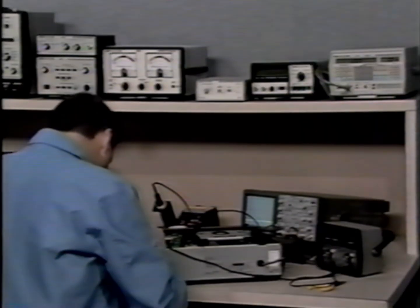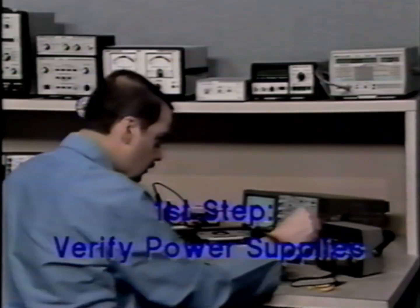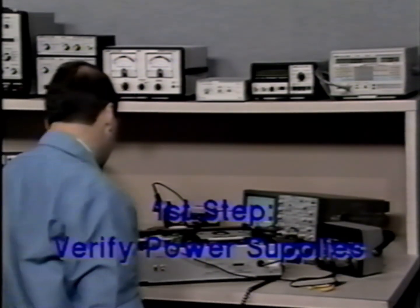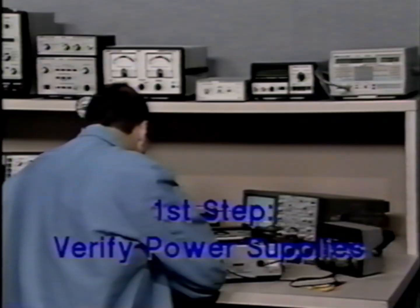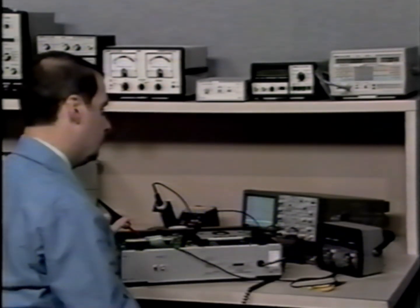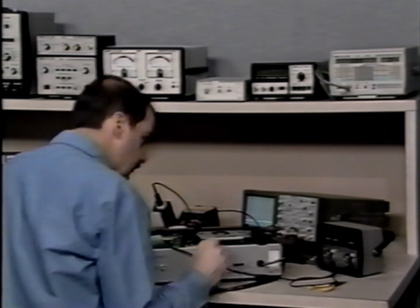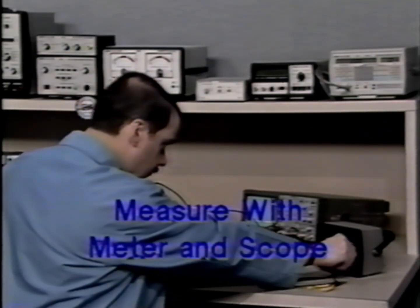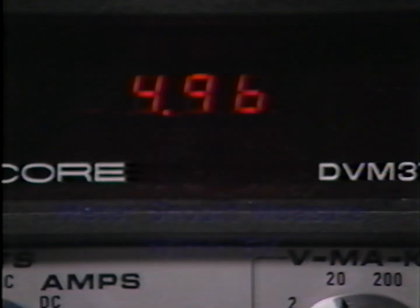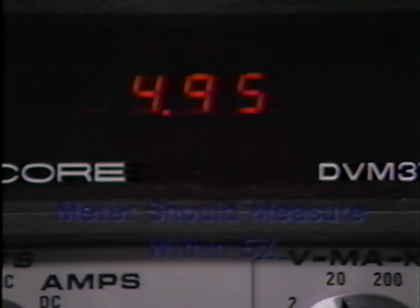The first step in troubleshooting any microprocessor circuit is to verify the power supply levels. Without proper power supply voltage levels, the microprocessor operates either erratically or not at all. The DC supply should be measured with both a meter and with an oscilloscope. The meter should read within about 5% of the values shown on the schematic.